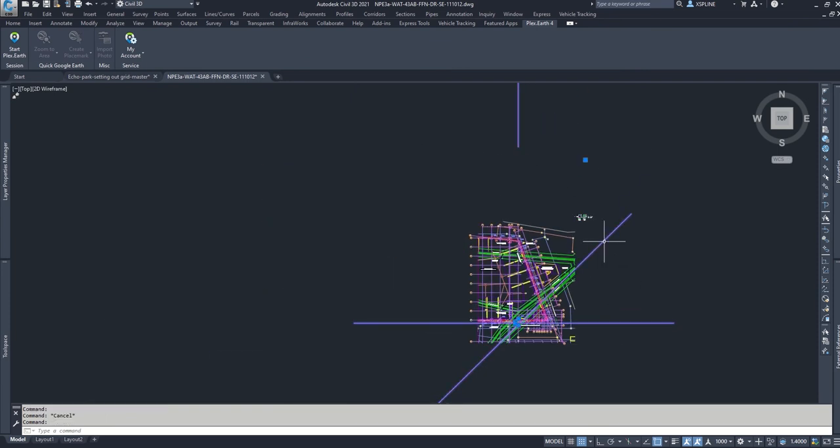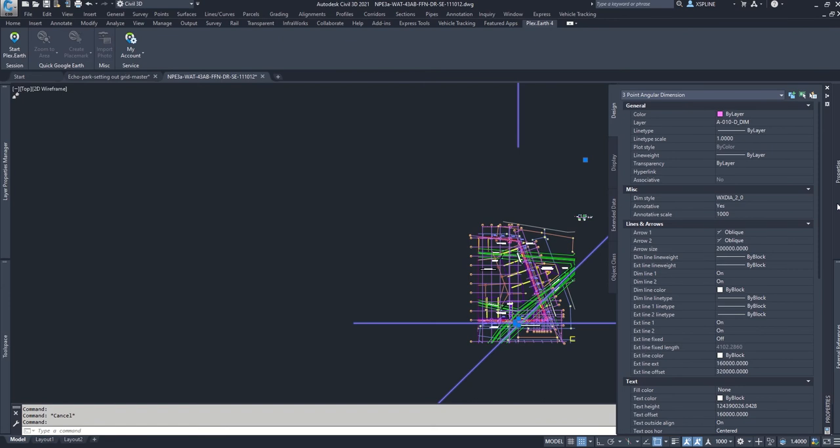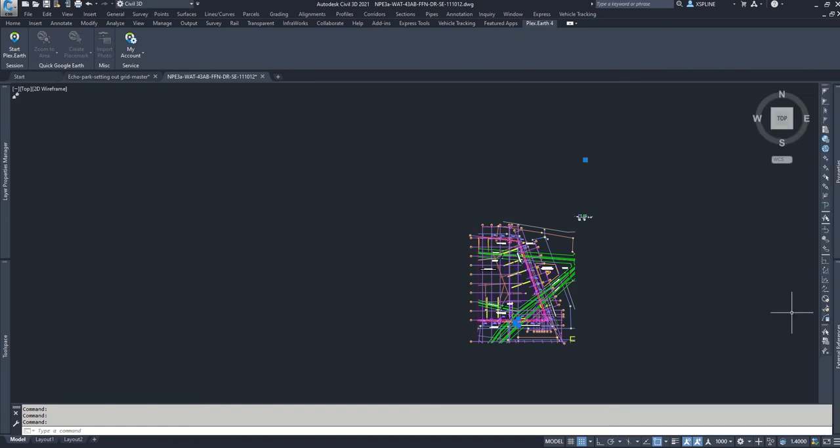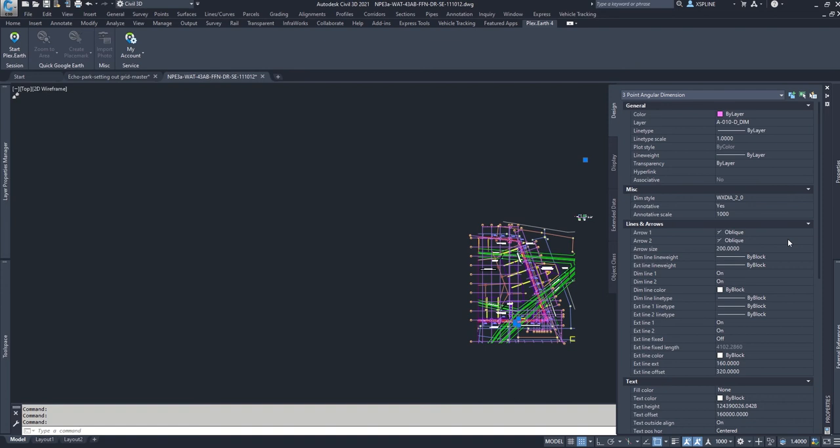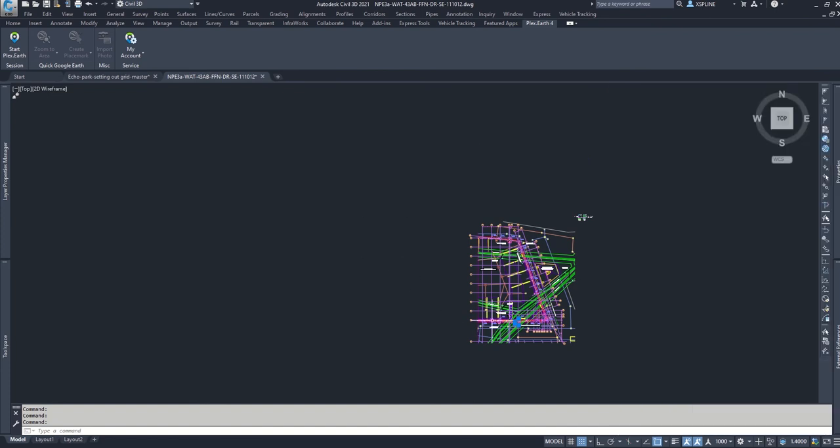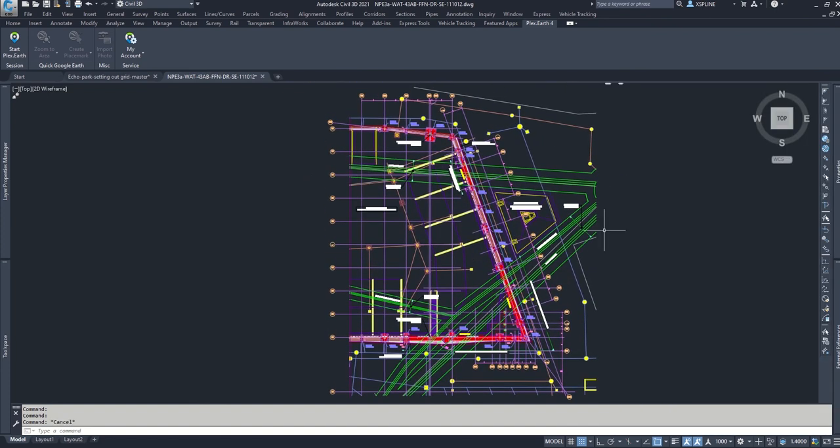There are some extension lines here that could be picked up as well. When you see some large numbers, just divide them by 1,000. So here, 200, 160, 320, and that's got those. I think there's an extension on a text as well. Text alignment is there, text height there, text offset 160. Right, so you have that now. That's basically the drawing scaled.